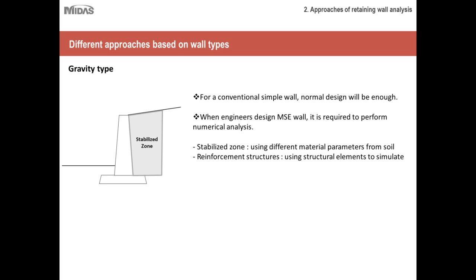So since MSE wall in itself is constructed as different modules put together in stacks, so basically it is a segmentally constructed structure, so you must consider its actual construction procedure, and at the same time you must use proper element types in order to simulate the same behavior.